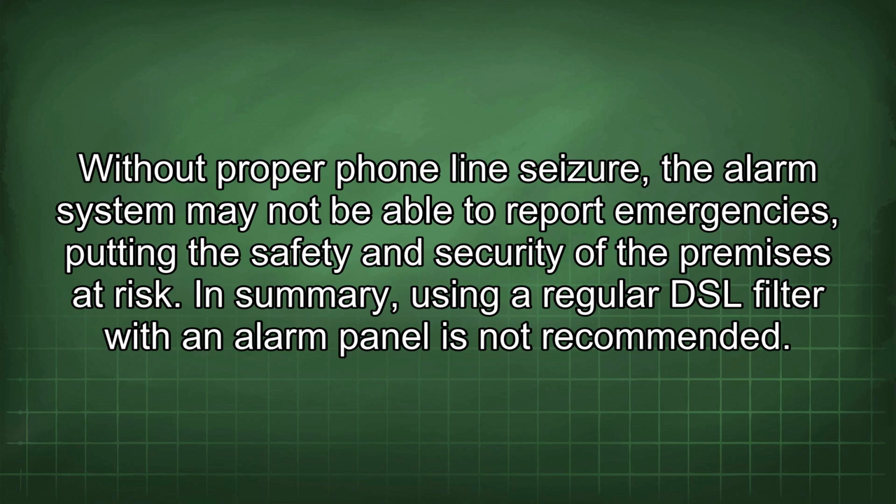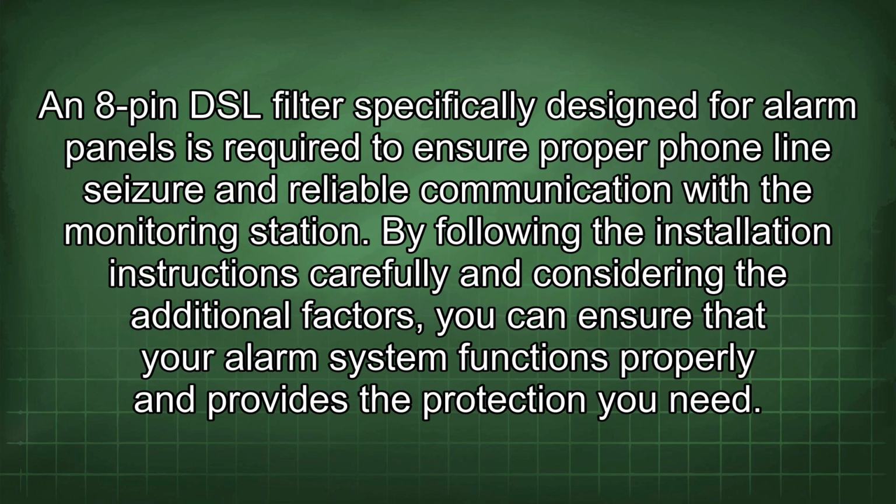In summary, using a regular DSL filter with an alarm panel is not recommended. An 8-pin DSL filter specifically designed for alarm panels is required to ensure proper phone line seizure and reliable communication with the monitoring station. By following the installation instructions carefully and considering the additional factors, you can ensure that your alarm system functions properly and provides the protection you need.